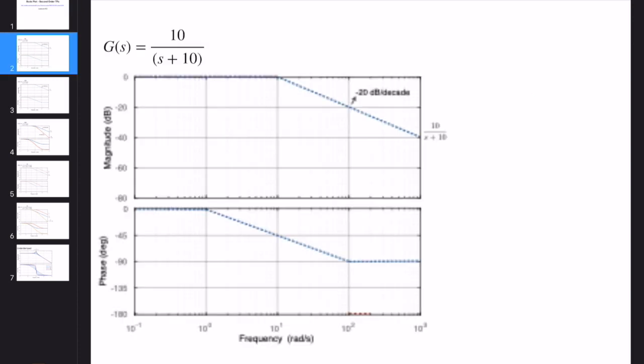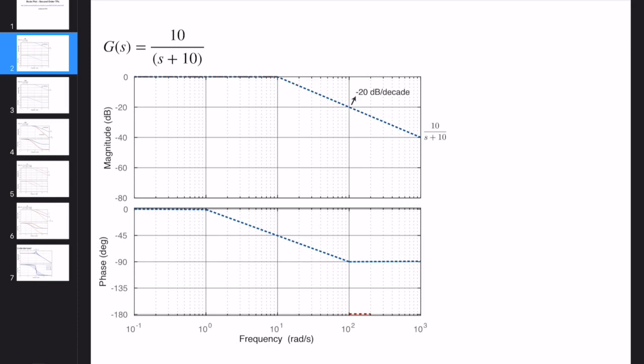Okay, let's assume that we have a first order low pass filter which has a pole at -10 location. So what we need to do? We need to first detect the time constant and cutoff frequency for this low pass filter. Okay, let's start with this. We know that omega c is equal to the magnitude of the pole, which is 10 radian per second, and time constant is simply equal to 1 over 10 second.